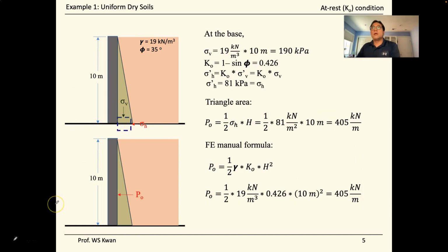So this formula only works for 1-layer systems. That's why I recommend you develop a habit of always drawing out the stress diagram. It helps you see how to calculate the forces at different soil layers, which we'll cover next.